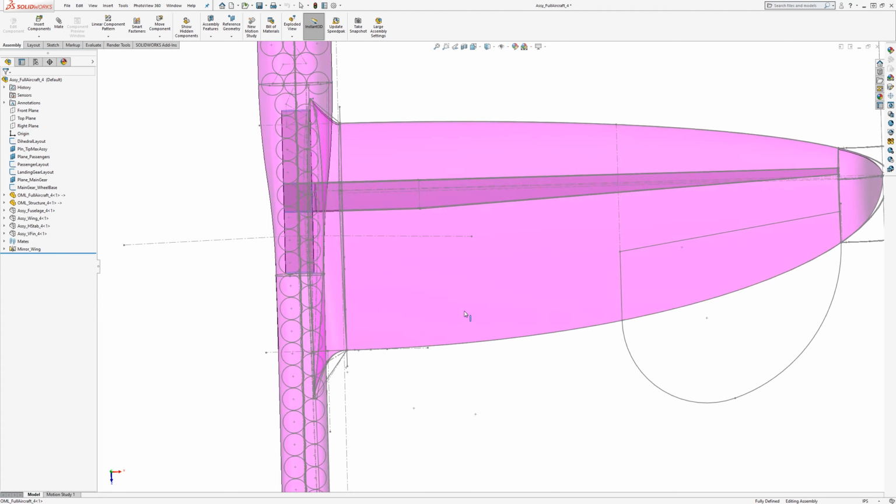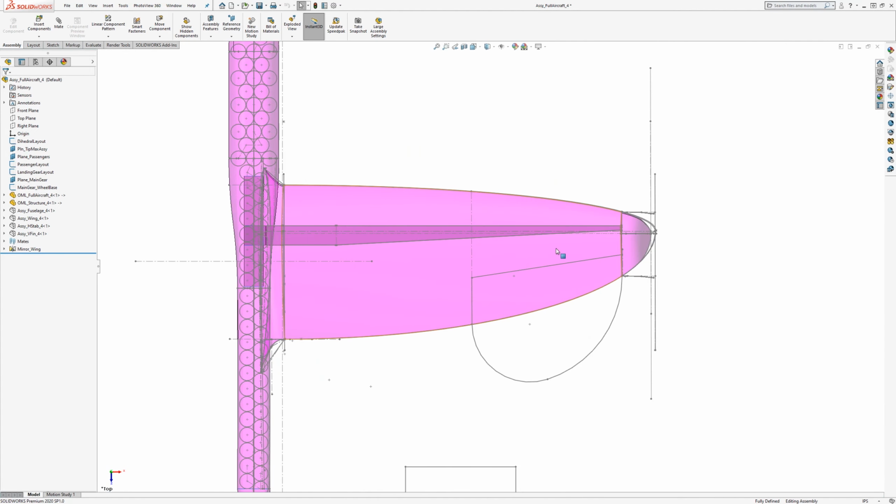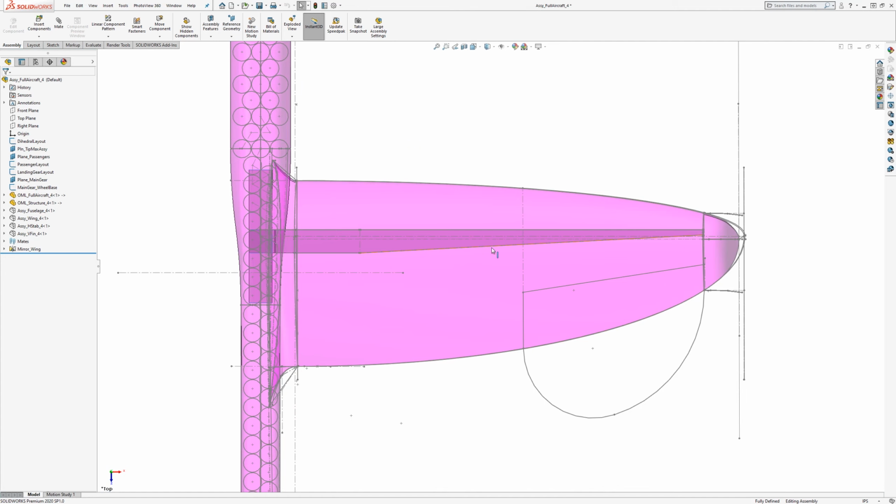From the top, this portion, the front one, is straight, parallel to a front plane, and the inboard section of the spar from the back is also parallel to a front plane, but the part that tapers starts a little farther outwards, and that part tapers to a point here. The reason for doing that, instead of having the taper go all the way to the inside, is that at that point you have a compound cut.